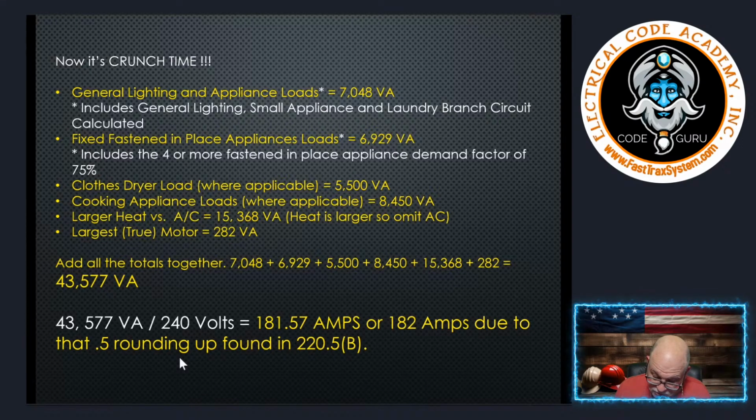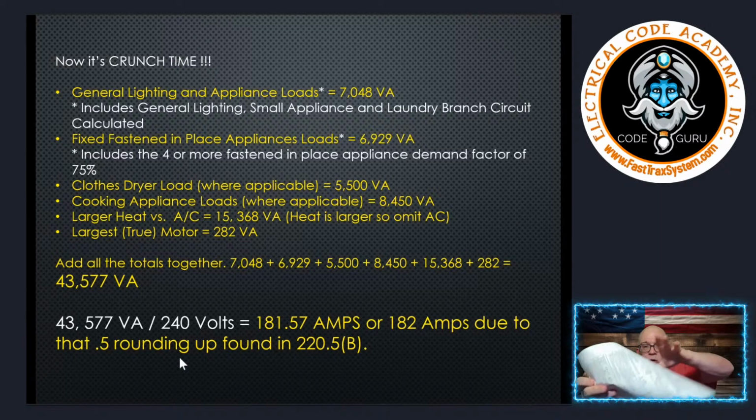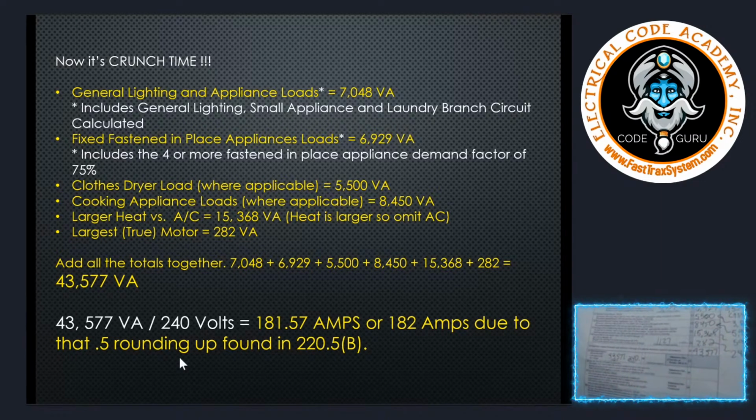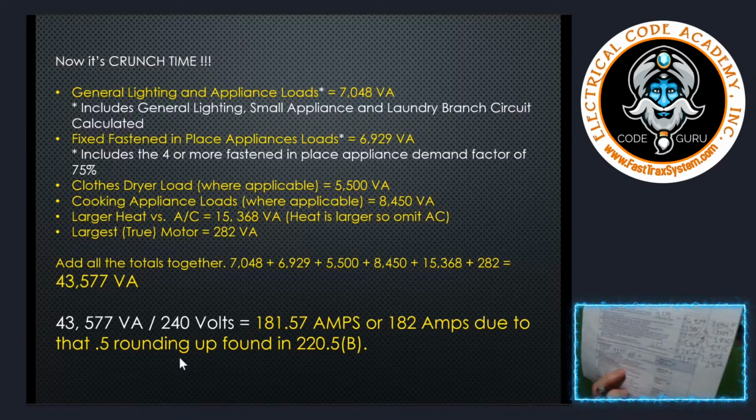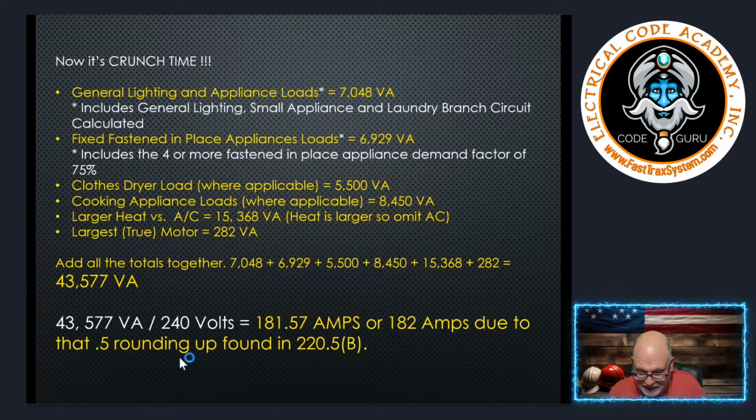We also know that it's a 240 volt system, so we write 240 down. And so we're basically doing the math right there. See it right here? So now we're going to just take 43,577 divided by 240.